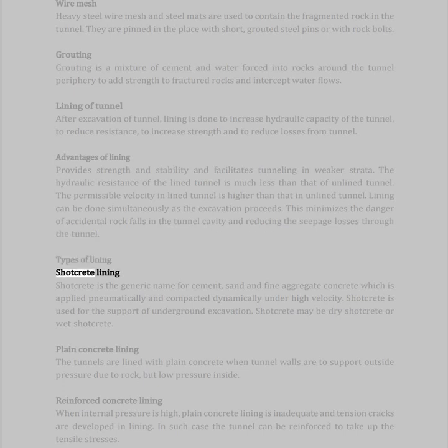Types of lining. Shotcrete lining. Shotcrete is the generic name for cement, sand, and fine aggregate concrete which is applied pneumatically and compacted dynamically under high velocity. Shotcrete is used for the support of underground excavation. Shotcrete may be dry shotcrete or wet shotcrete.